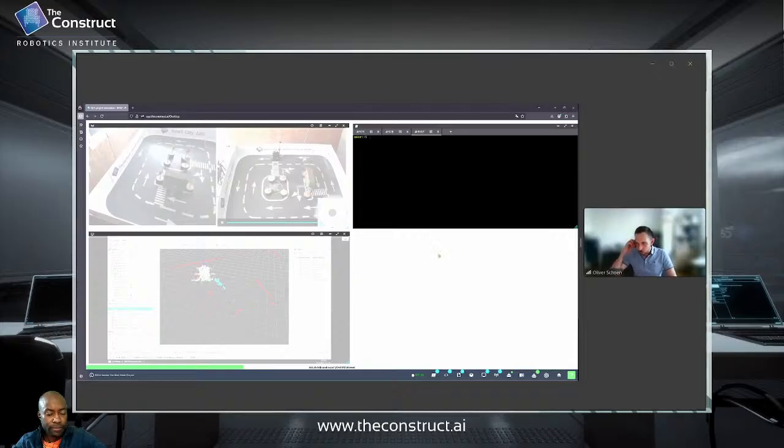In order to do so, we can use a command line tool from the TF2 ROS package, tf2_echo. When we quickly look at the help, you can see that we need to give it a source frame and a target frame. We can also set the echo rate. But in order to get the transformation from one frame to the other, we have to provide both frame names, and then we can get the actual transform. Still, we don't know which frames we are looking into in the very beginning. In order to find that out, we can use another tool, which is from the TF2 tools package.